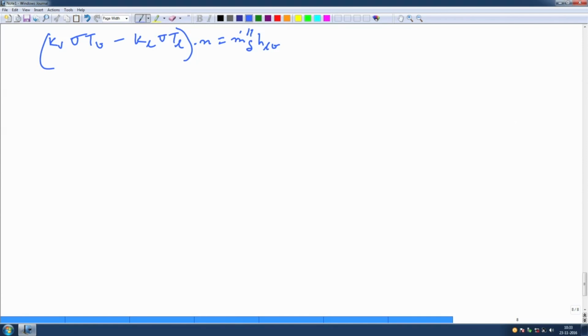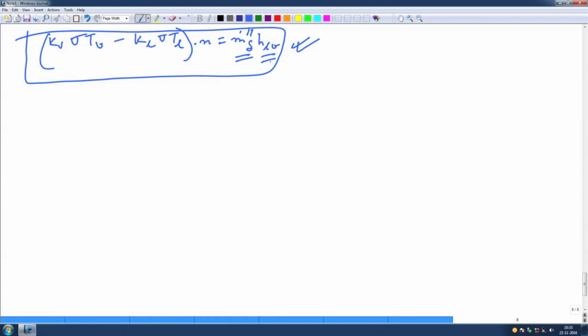So, it is basically two heat conduction terms that you have, and the corresponding mass transfer due to evaporation or whatever, and the corresponding latent heat. Okay. So, we can arrive at this particular form just by making those assumptions. This is also widely used, in most of the cases you will use this. So, this is the conduction equal to whatever mass is taken away by this.